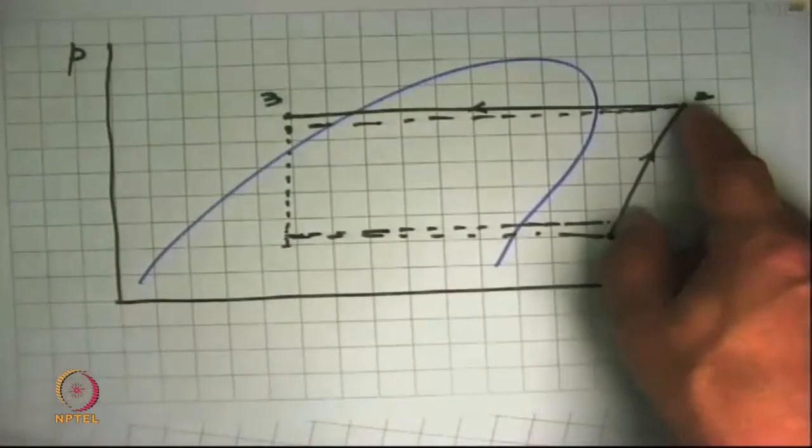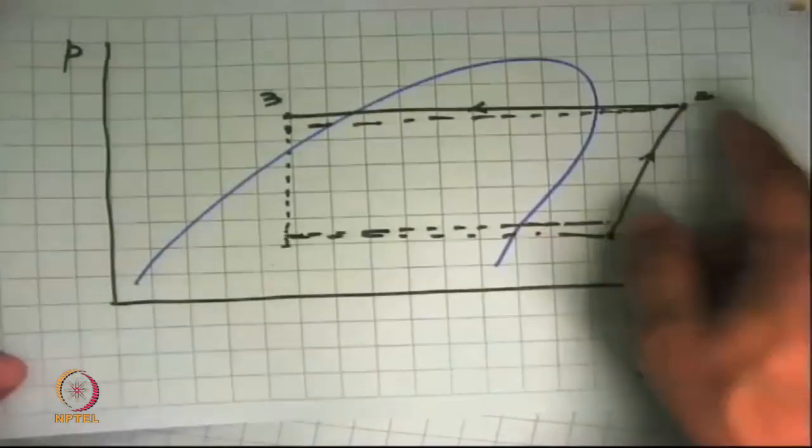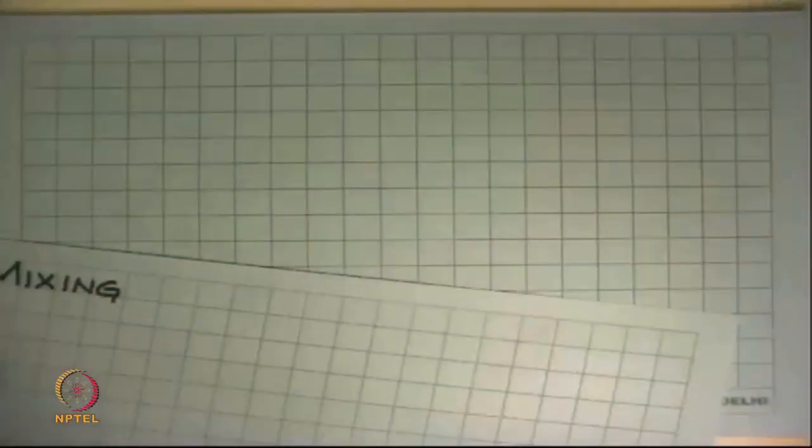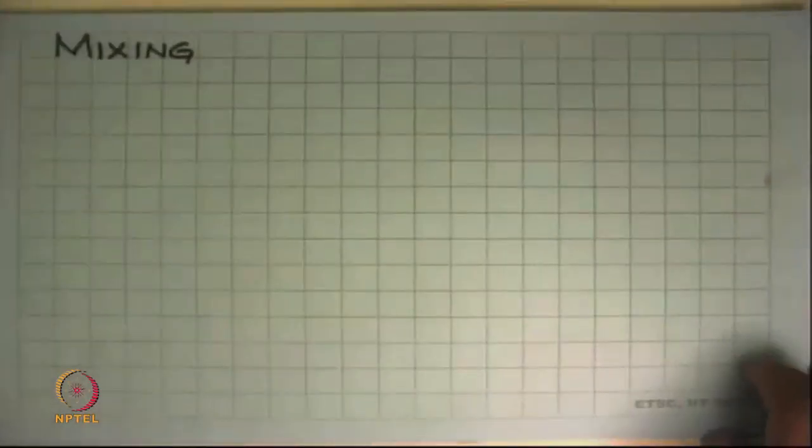If it is a water system, then all the pressure drop in the pipe has to be taken care of by adequate pressure build-up in the pumps. So your pump design, your compressor design, the fan design, they depend on the design of the pipes and also pressure drops which will take place within the cooling coils or some heating coils or some other tubes. So that's where this is important.